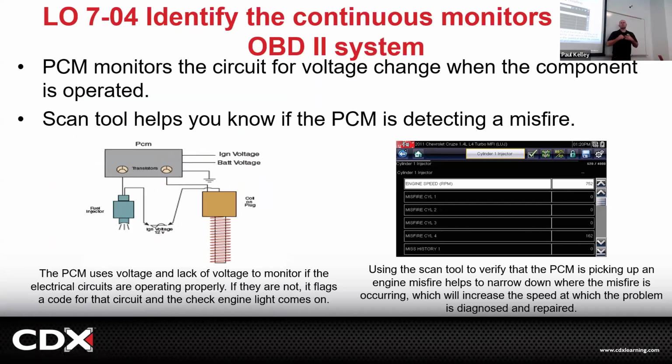I like circuit type DTCs because when a circuit DTC sets, I know that I'm in the circuit, right? I'm testing the wires, I'm testing voltages. I might even be able to do an active test with the scan tool where I fire the injector manually. Makes sense? But then there's other types of codes, like what I was focused on here.